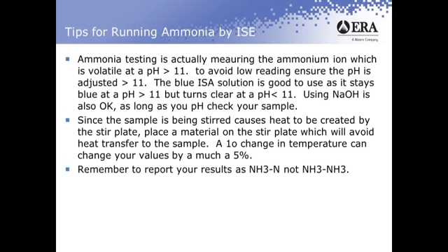One of the important things to remember is that with these high-performance electrodes, the instrument manufacturers will tell you not to rinse the electrode itself with DI water. The pressure of the DI water will cause that electrode to drift, and once it drifts, you're going to have to perform your calibration all over again. So what they recommend is to not use your DI bottle to rinse it, but to dunk that electrode into a container of DI water and then dab dry with a chem wipe.